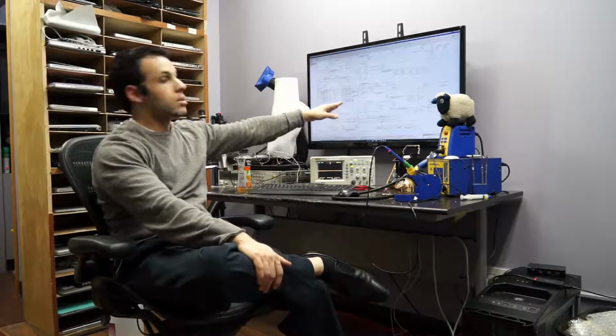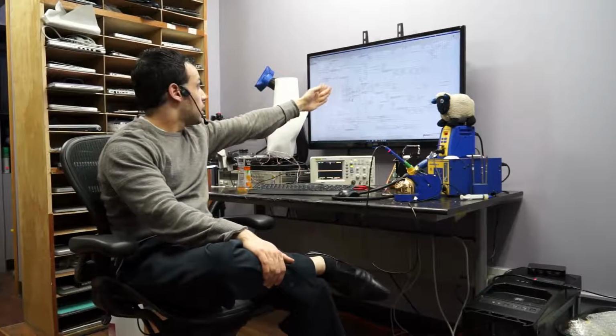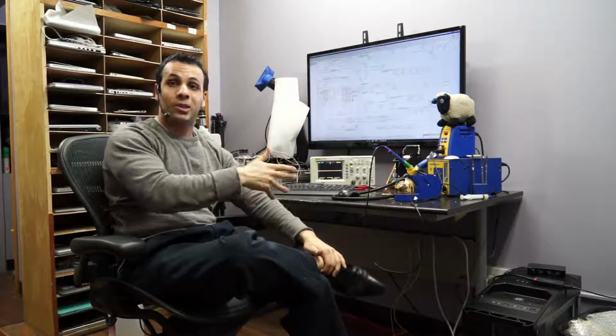And if any one of those resistors or any of the traces to these resistors, which are, again, high voltage, close to the battery and close to the source of the charger, those are going to be spots where, if water hits there, you're going to see big explosions and nastiness on the board. Those are spots that you should look at, and those are spots that will usually be screwed up if your battery or your charger's not working.